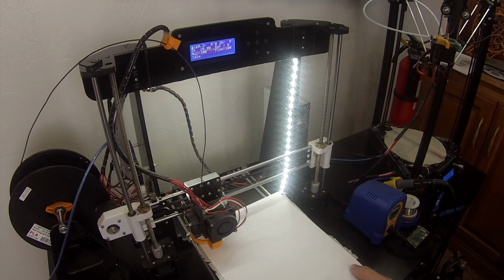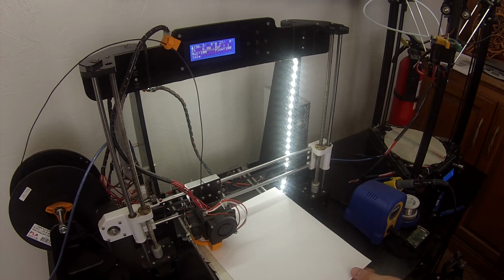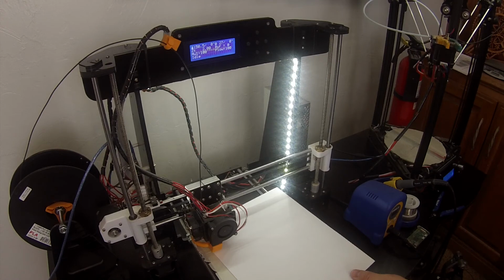So using my left hand, I'll move it. Using my right hand, I'm adjusting the print controls on the computer, setting things at first to a 1 millimeter Z increment, because I expect to be approximately 1 centimeter above the bed right now. Looking down from the side to see how close the print head is to the paper. Okay, we're really close now, so I'm going to change this down to 1/10 of a millimeter in Z for each input I give. Moving the paper.